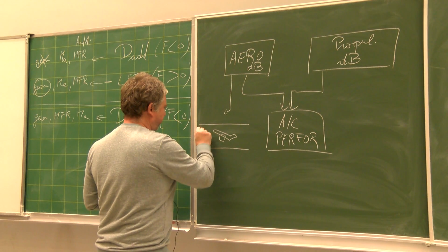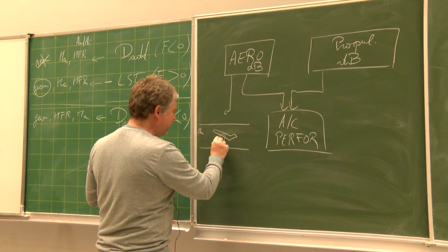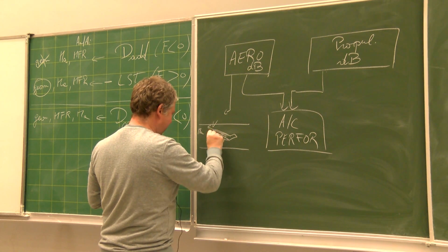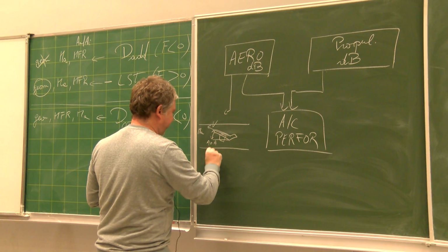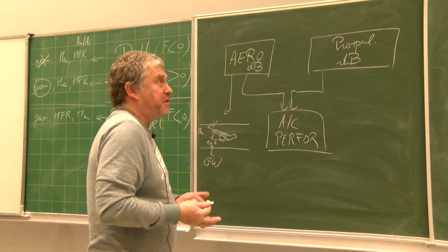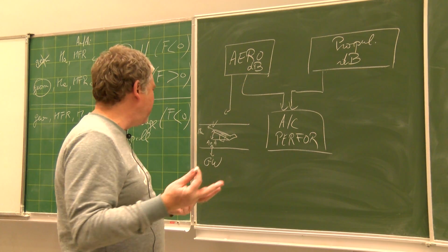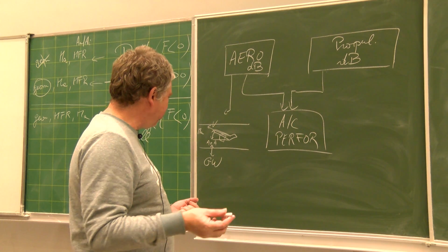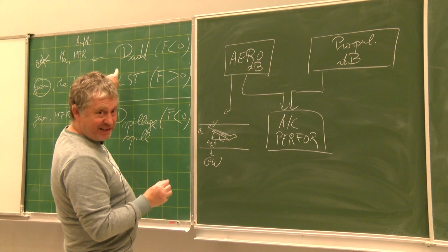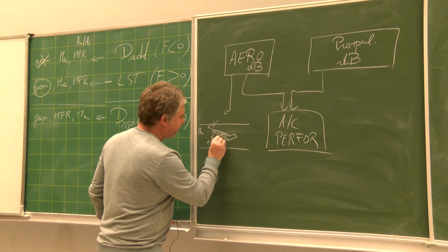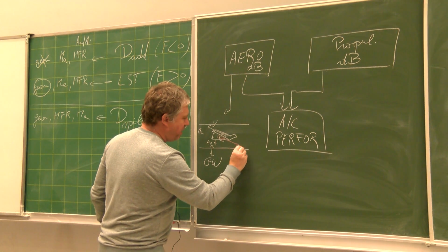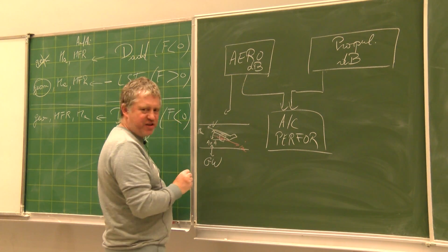We need to test it, of course, for different flight Mach number. We need to test it for different, let's say with a certain speed, angle of attack. And this angle of attack is related with the aircraft gross weight. Let's say its structure, its payload, the amount of fuel you have on board. But it needs also to have, due to these features, the engines. And the engines must be with a certain mass flow rate going through the engine.